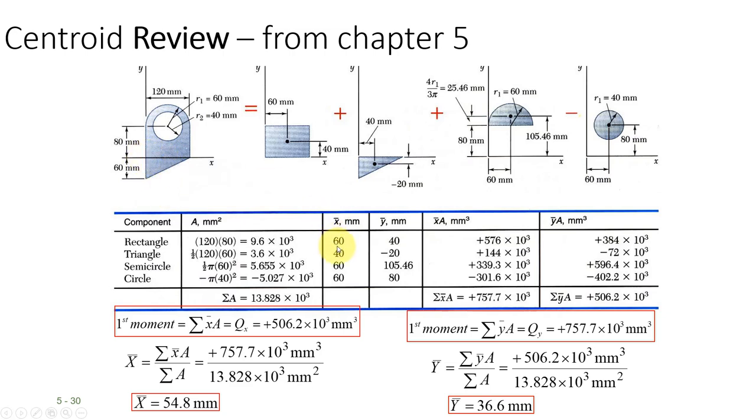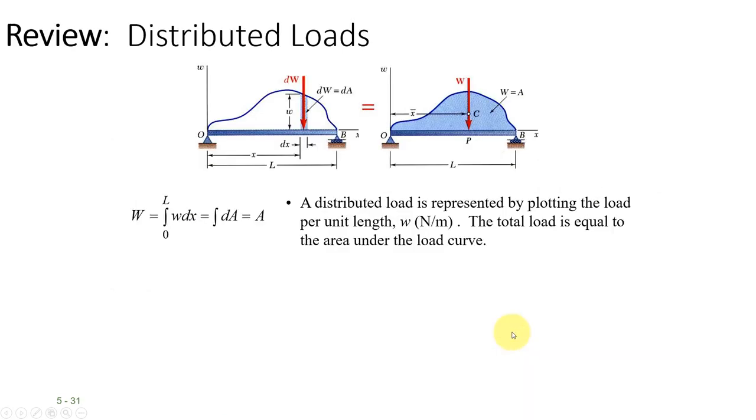So we looked at how far away it is, and the area ratio is the same as the mass ratio, same as the force ratio. If you add this all together, you found that distance through a moment calculation, r cross f. You have each little bit, you add up all of the r cross f's, and then you can get what radius it feels like. Okay, so instead of y times a or y times force, this is going to turn into r squared m instead of rm, is the idea.